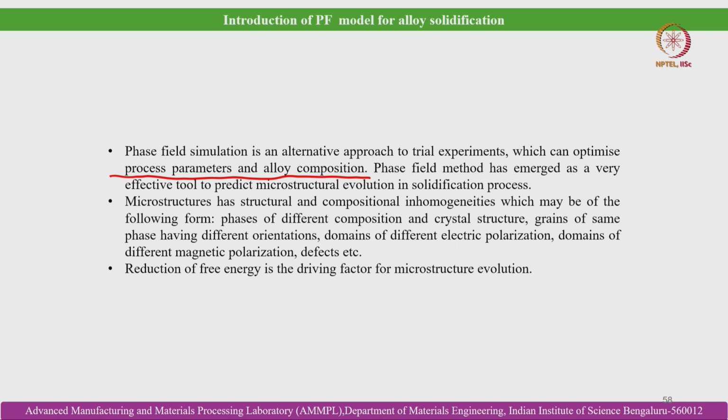So, the phase field method has emerged as a very effective tool to predict microstructural evolution in solidification processes in the last decade or so. Microstructures have structural and compositional inhomogeneities which may be of the following forms: phases of different composition and crystal structure, grains of the same phase having different orientations, domains of different electric polarization, domains of different magnetic polarization, defects, etc. Okay. So, reduction of free energy is the driving factor for microstructure evolution that is considered to simulate the microstructure evolution adopting the phase field model.